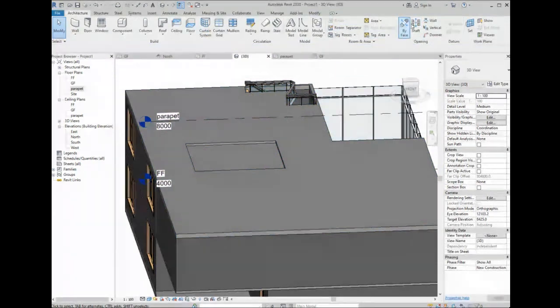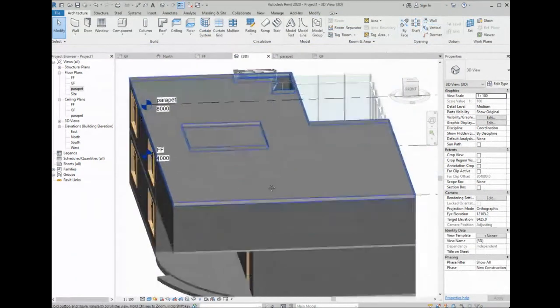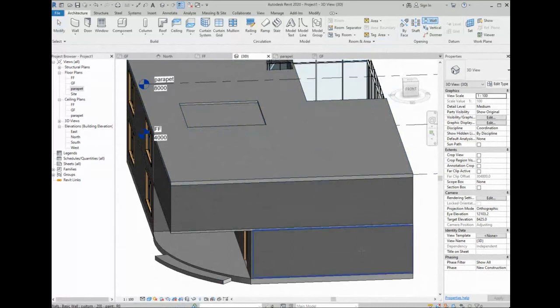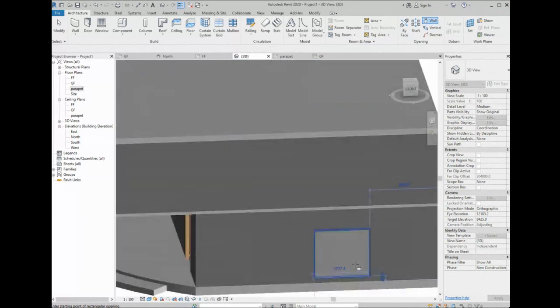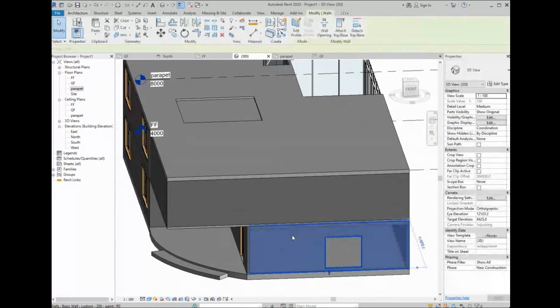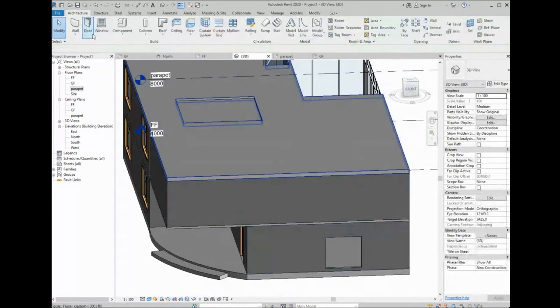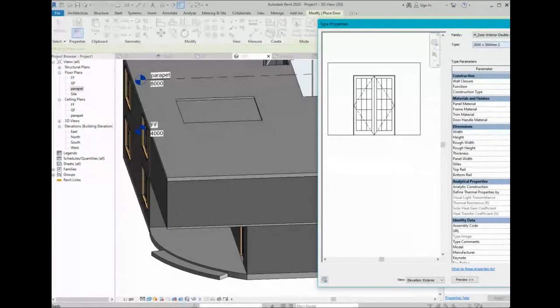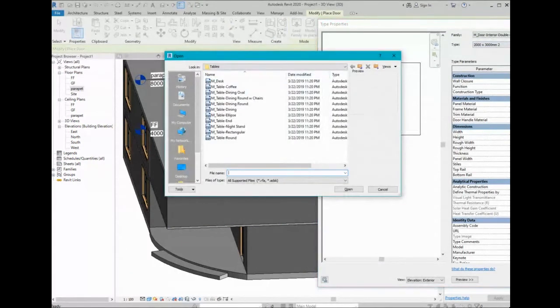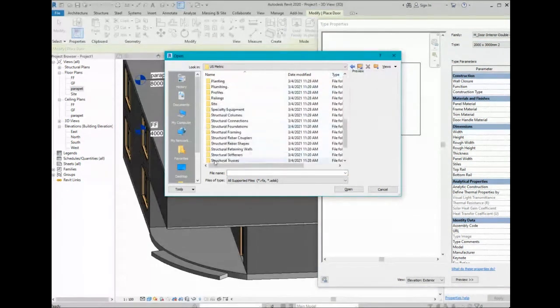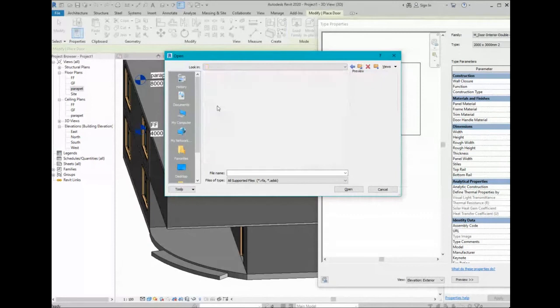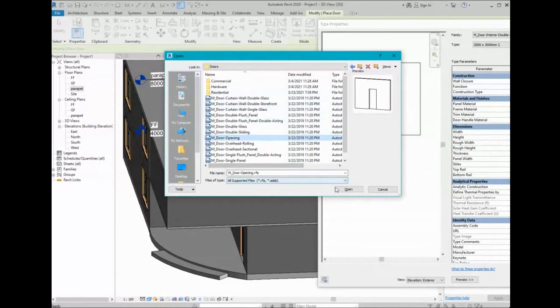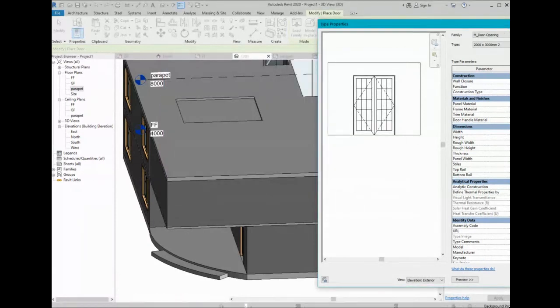Thank you. Okay. So for the openings in the walls, we have 3 types. We can either select wall and then select the surface and draw the opening this way. So you have an opening. The second way is to add an opening as a door. So I'll go to door, edit type, and then you will go to load. And from doors, you will find an opening. So let's go to doors. And you will find here that you have an opening. Okay, so both ways are correct.